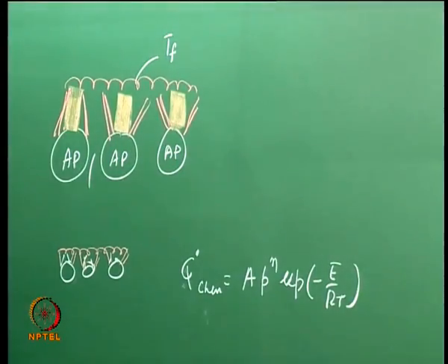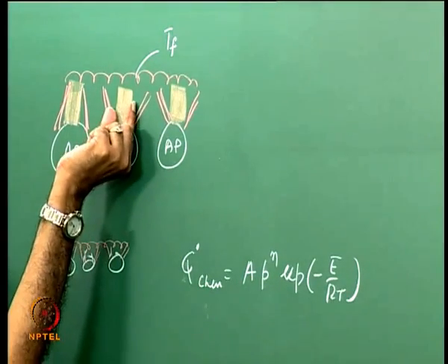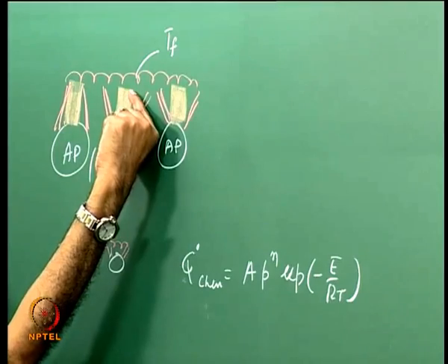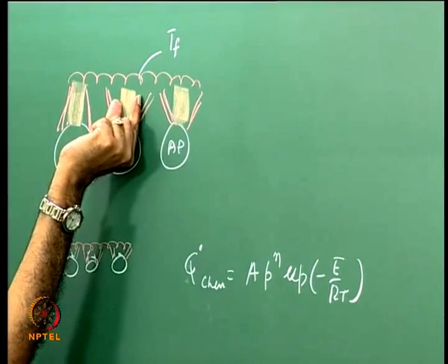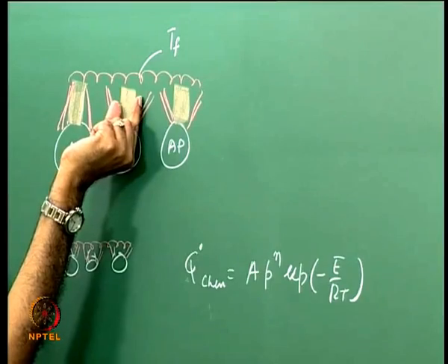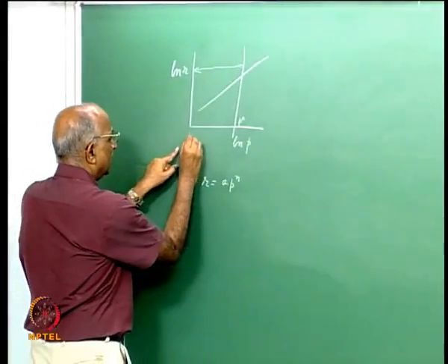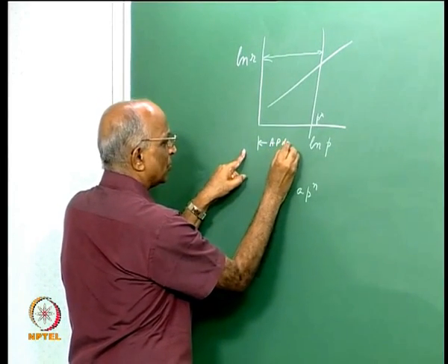Therefore, at lower pressures I have a lesser amount of energy getting liberated, or this becomes a controlling parameter, because this fellow still generates vapor but this fellow is missing, therefore this is what is controlling. Therefore, at low pressures I can say that chemical kinetics or AP decomposition controls.